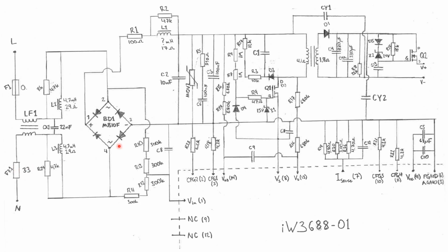On the secondary side, I would measure the secondary side of the isolation transformer for continuity. I would make a diode measurement on D1, measure the capacitance on the electrolytic caps here, which are one of the most failure-prone parts on an LED driver. Also, Q2 here can be checked for short, and it could also be good to measure the diode drop of the body diode here.